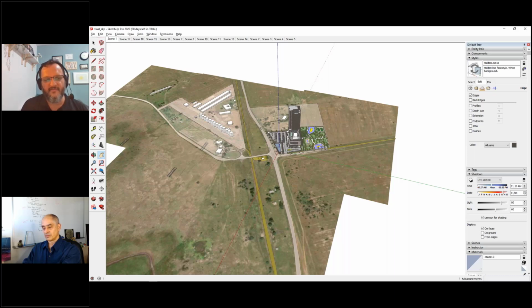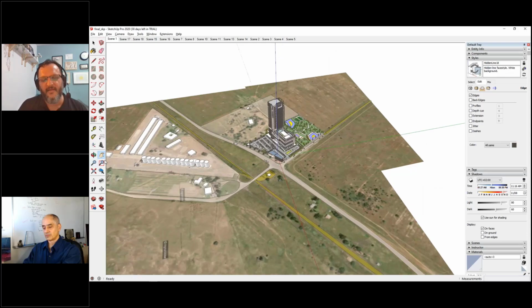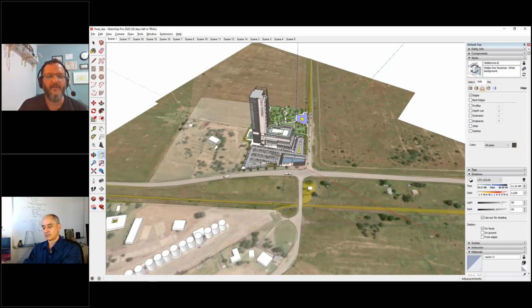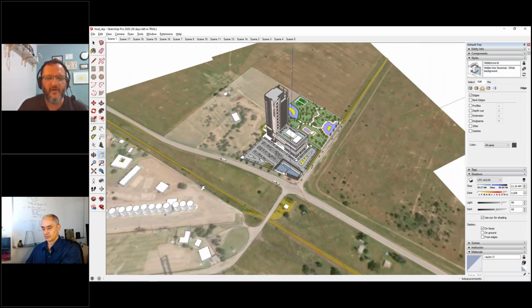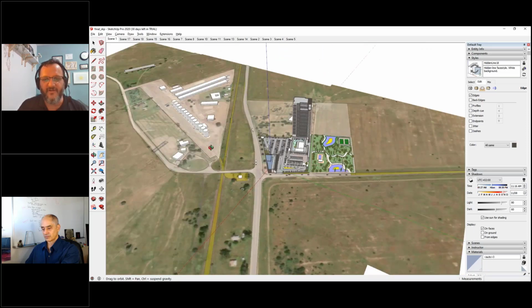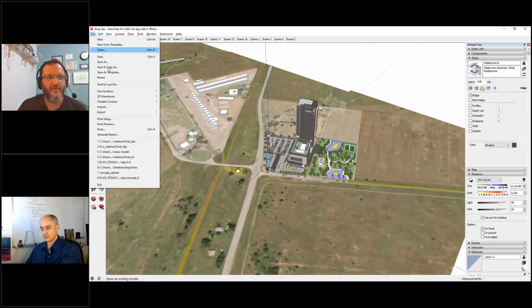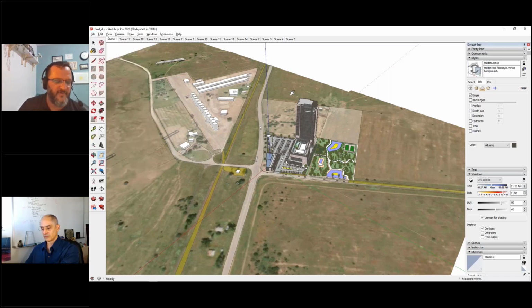However, it gives you instant GIS or rough GIS and visual of that area. So you can start accurately before a surveyor has gone out to your site to gather that type of information, instantly through using this function called add more imagery in the geolocation function in SketchUp, which is a very, very powerful feature for any design architect.